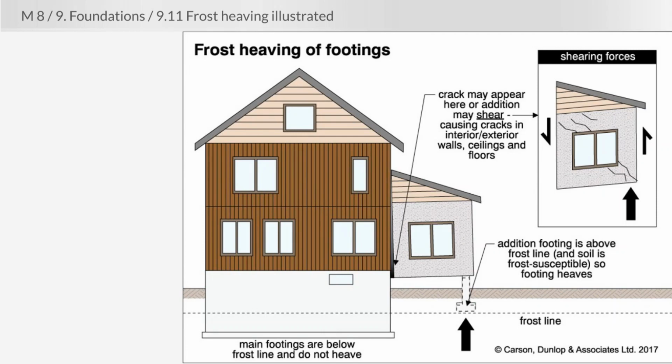However, very often in a real winter situation, when temperatures are below zero for 2 or 3 weeks at a time, frost may actually go below the accepted frost line to the real frost line, at least real for that winter. Nevertheless, the building codes simply require the footings to be placed below those accepted frost lines.